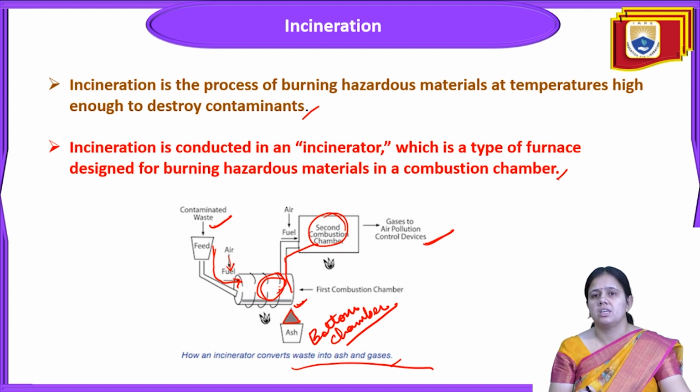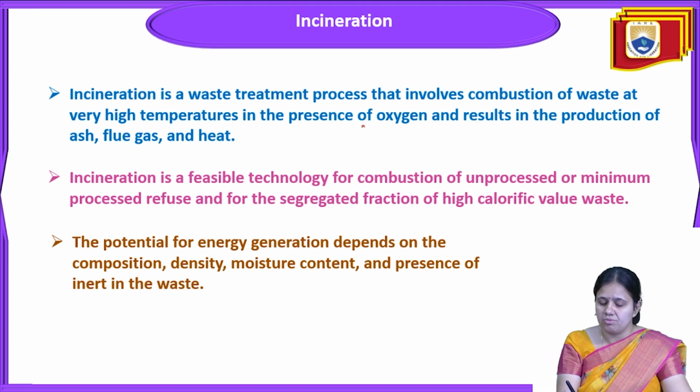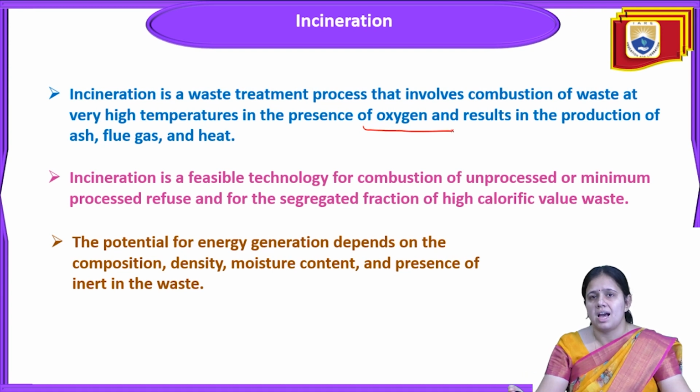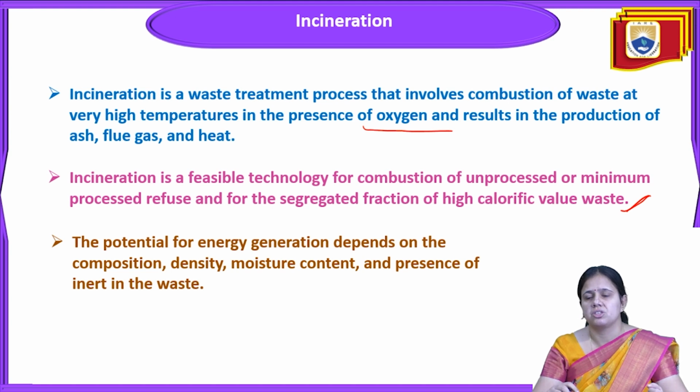Incineration is conducted in an incinerator, which is a type of furnace designed for the burning of hazardous material in a combustion chamber. Incineration is a waste treatment process that involves the combustion of waste at a very high temperature in the presence of oxygen and results in the production of ash, flue gas, and heat. Incineration is a feasible technology for combustion of unprocessed or minimum processed refuse and for the segregated fraction of high calorific value waste.